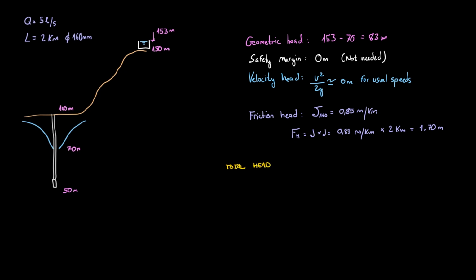We add them up and we find that the total head for the pump is 85 meters. Now, if you just wanted to double check, you can crunch the numbers and you will see that the velocity just produces a very small head.